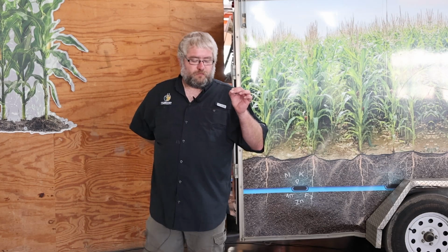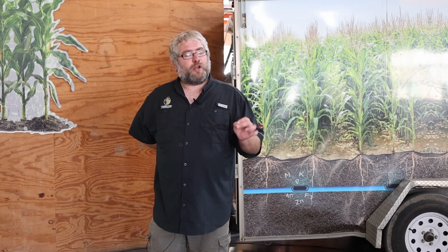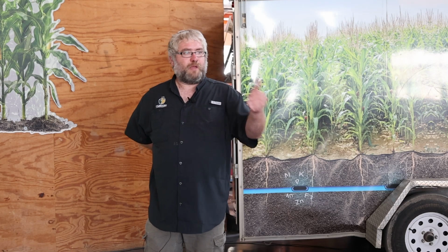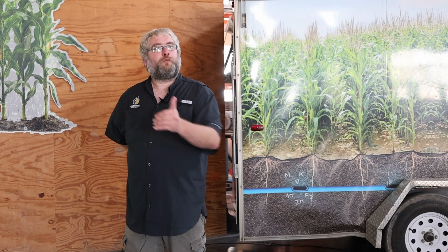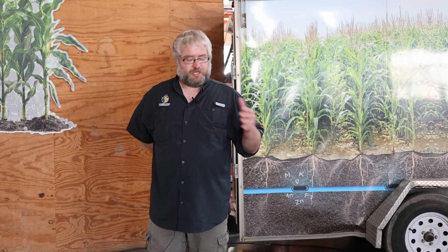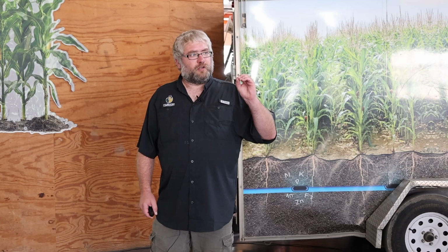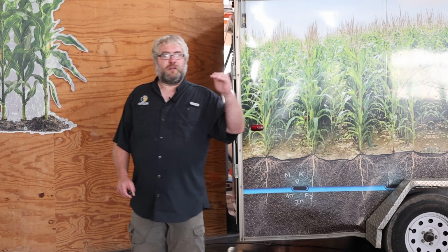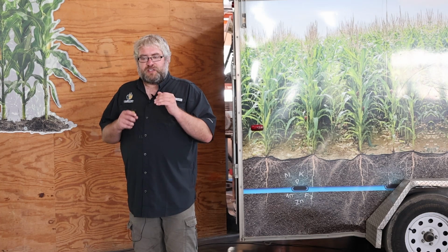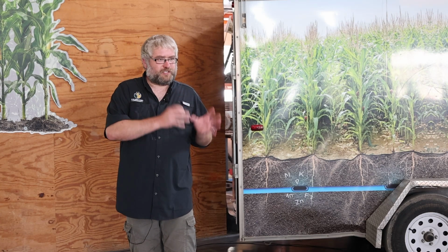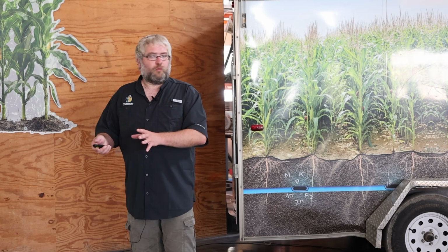Then we can work with treatments and look at what treatments we can apply and how they may affect the soil water mineral solution before we spend money and apply it. We can dial in the rates, learn where our no-go zones on pH are, separate out what's a decent water we have a good chance of amending and having success with, and the ones that need more work.